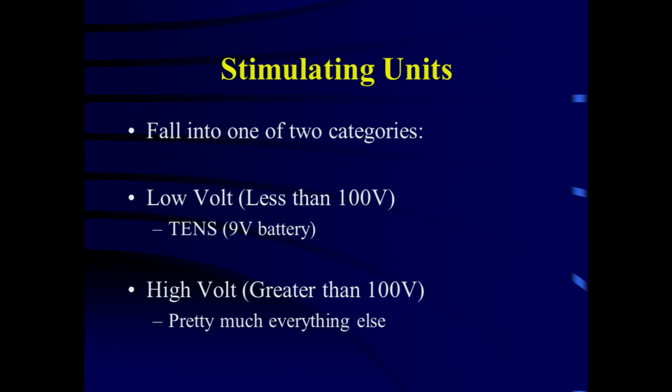As current levels go high, it becomes difficult to open a circuit, whereas voltage just collapses from one to the other. So quite often we use electrostatic storage rather than electromagnetic storage, and you will find a lot of capacitors used for pulse generation.